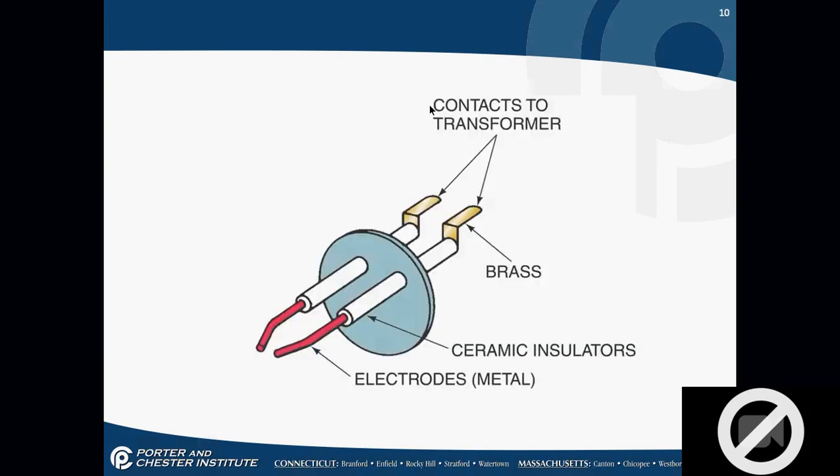The transformer connects in, regardless of what type of transformer we're using, to some brass leads or brass connections on the back of the electrodes, or it uses a spring that clamps down onto the electrode rods that come out of the back on some. So sometimes you'll see the brass and sometimes you'll see the aluminum or the stainless steel. That's what connects to the transformers. It's usually spring connects. Most often we don't have wire connections there. There's a few burners that do, but it's not often.